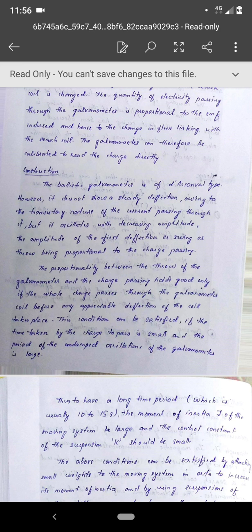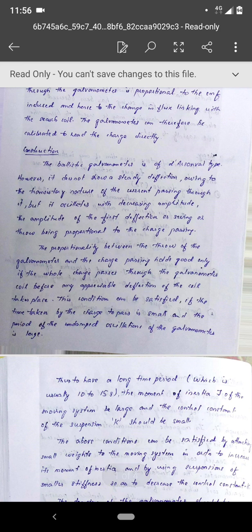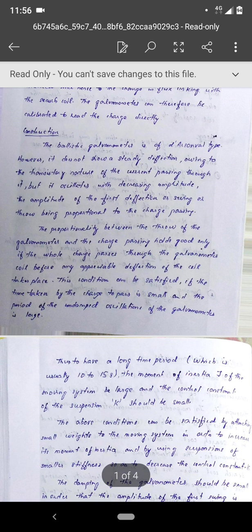Moment of inertia means that it is very hard to rotate. So when the pointer is stationary, with theta zero and no change in deflection, even if there is a change in flux, it is very hard to rotate the moving part. But when it starts deflecting, the swing of that motion is very hard to stop as well. There will be oscillations, which are damped, but they will take time to die out.